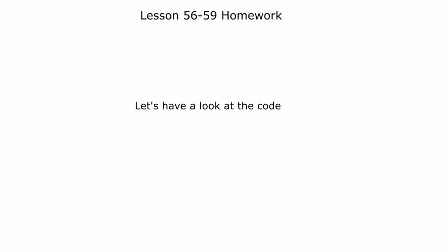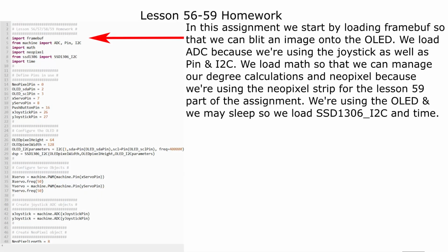Let's have a look at the code. In this assignment, we start by loading frame buff so that we can blit an image onto the OLED. We load ADC because we're using the joystick as well as pin and I2C. We load math so that we can manage our degree calculations, and NeoPixel because we're using the NeoPixel strip for the lesson 59 part of this assignment.